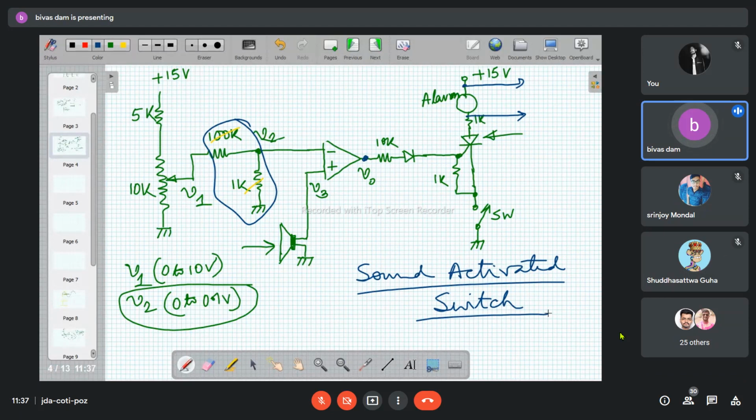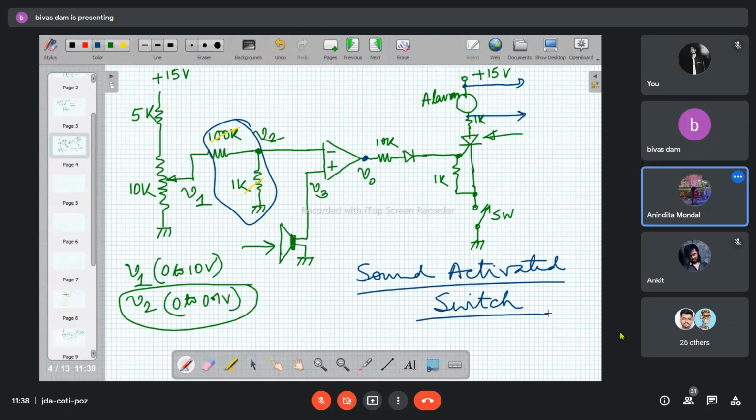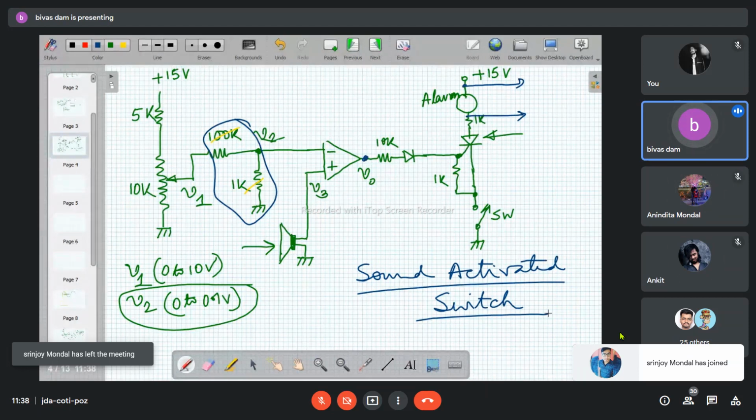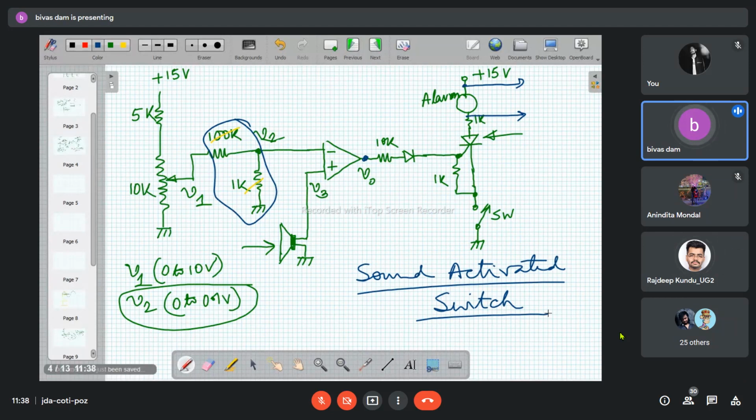You are suddenly getting that flash of light. Where is it from? So from some electrical signal, it is activating the flash. No, physically where is it coming from? There must be some discharge. So some capacitor discharge type of thing is there. Yes. Some charge is stored in the capacitor, and when you press the flash switch or the camera switch, the two terminals of the capacitor are shorted. So almost instantaneously, the charge current is decaying, and that leads to the flash of light.